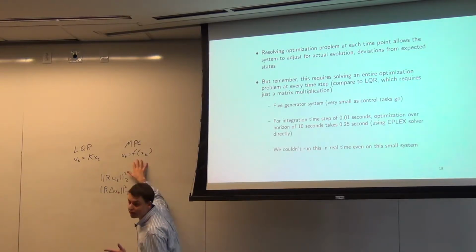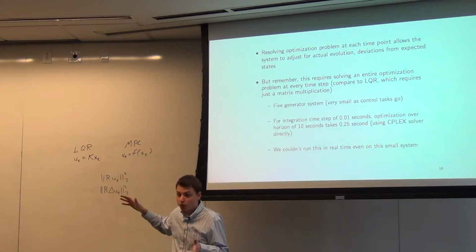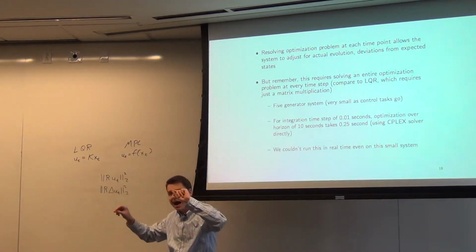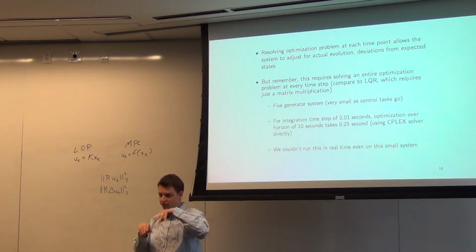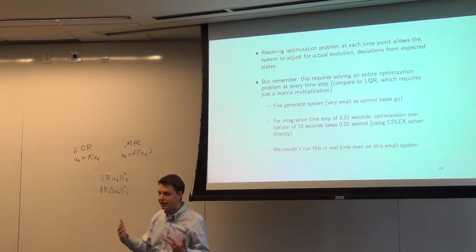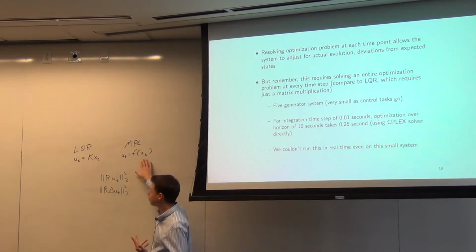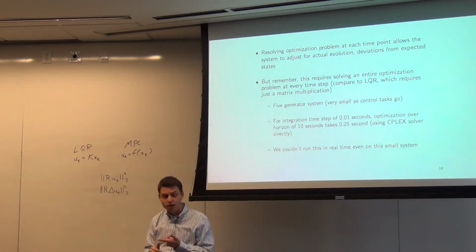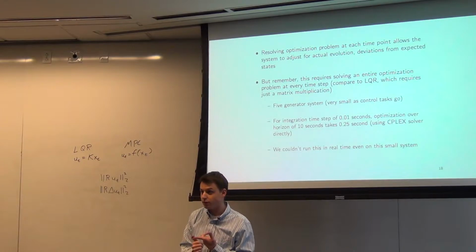MPC is a similar thing, where it's not really optimal anymore, but if you get far away, it'll plan a trajectory to get you back to where you want to be. You'll take the first bit of that, and you'll see what happens next, and you'll keep doing this, and that will tend to push you back toward where you want to be. So this feedback element can work very well in practice while, as I said, obeying those constraints that we have on our control.